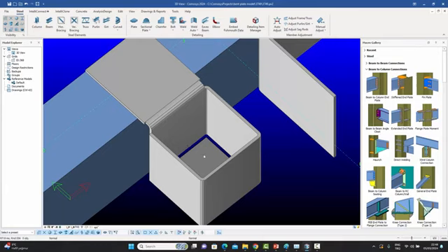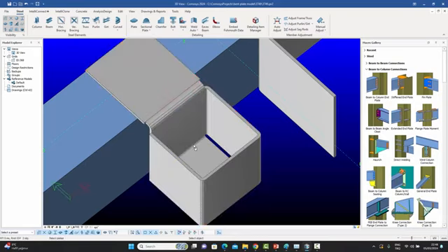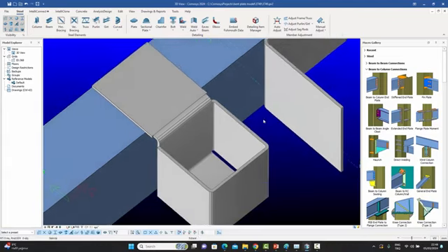And now for the final one, there's one lying at the bottom as well. I can go and choose the command again and say connect this one to this one. And it gives me four options this time because all four are touching or can touch theoretically. So I choose this one, and immediately I get this very complicated folded plate.